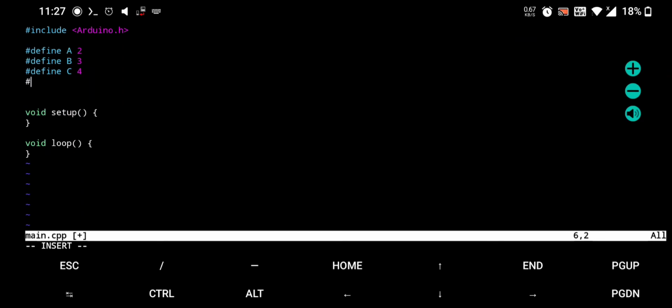Now we will have the output pins also. I will define the output using NAND logic as the NAND output variable, which is at pin 12. I have connected an external LED to this pin to see my output. And also we have the inbuilt LED for verifying the K-map expression, which is already declared inside the Arduino.h file.